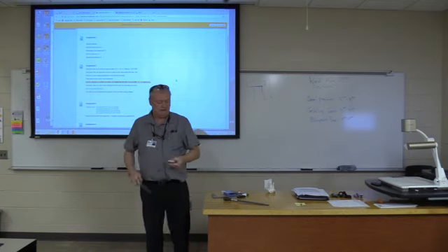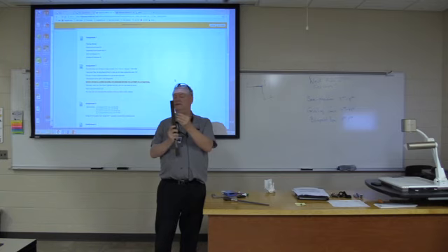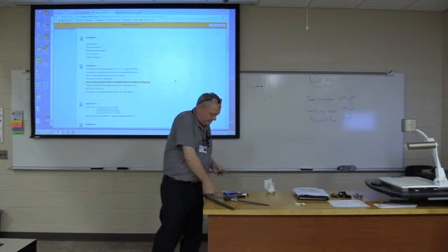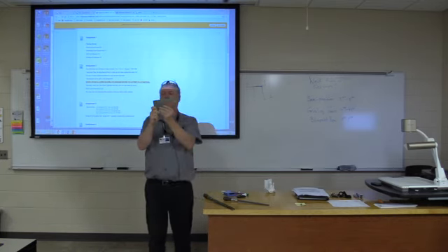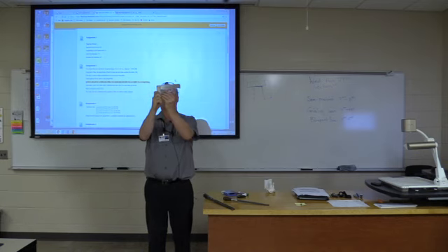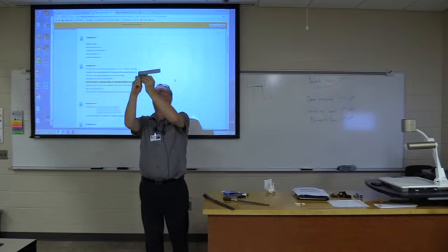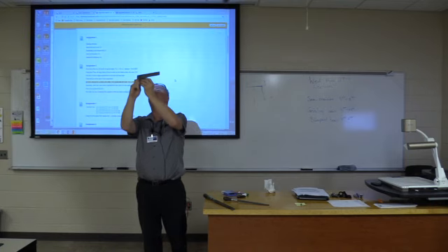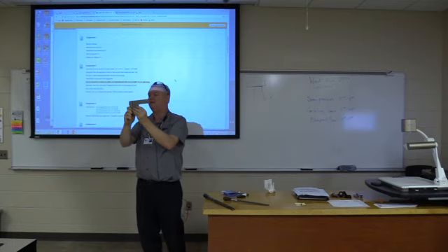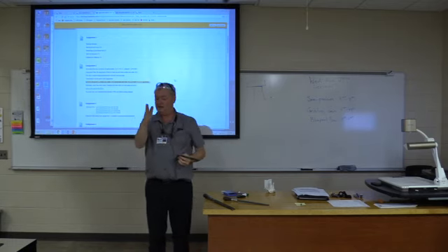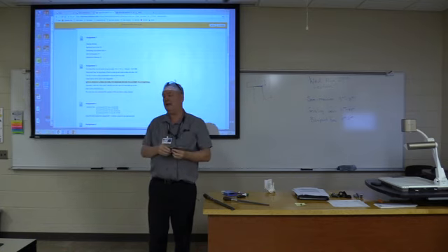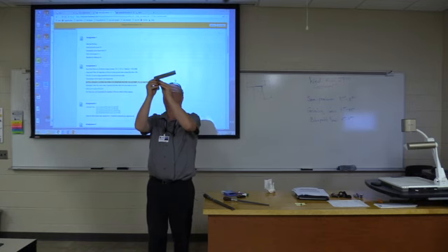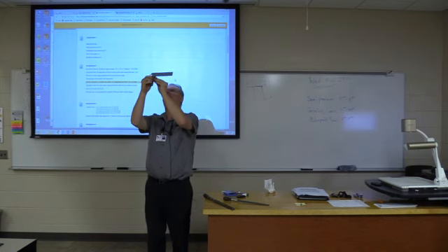So then at the same time, we want to make it perpendicular to the side as well. So that means I take the square, put it up against the part, and now look at it through the light. Oh, and that saw did a fantastic job. Very little on this. So this is perpendicularity to the edge, perpendicularity to the face. So the saw cut it nice and straight. There's very little gap or light showing through. But there is a bit of taper. Oh, this is even pretty good.